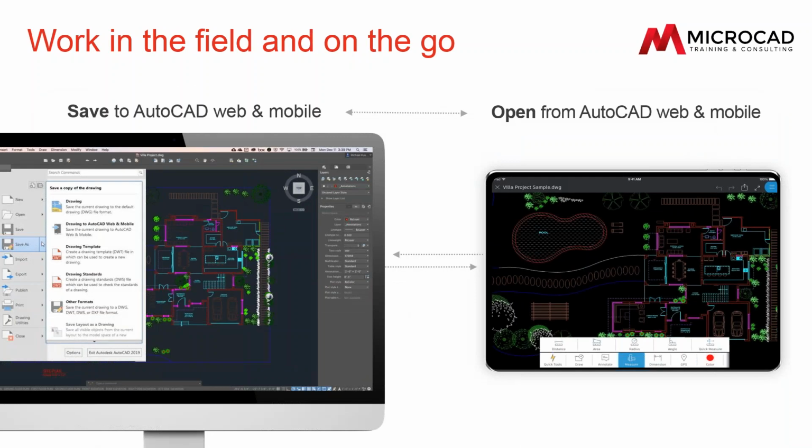All right, so in order to enable better workflows across desktop, web, and mobile, you'll want to take advantage of the functionality to access these DWG files in the Office and beyond on these apps. So you'll also be able to, inside of AutoCAD, go to the application menu, and in Save As, you'll see Save Drawing to Web and Mobile. And so this allows you to save those drawings in places where you'll be able to access them in all of these mobile applications. So this allows you to easily go from drafting on your desktop to drafting on your AutoCAD web browser, and then also those mobile apps and vice versa.